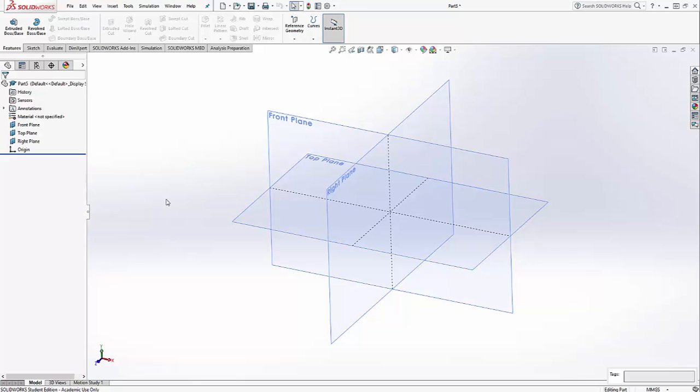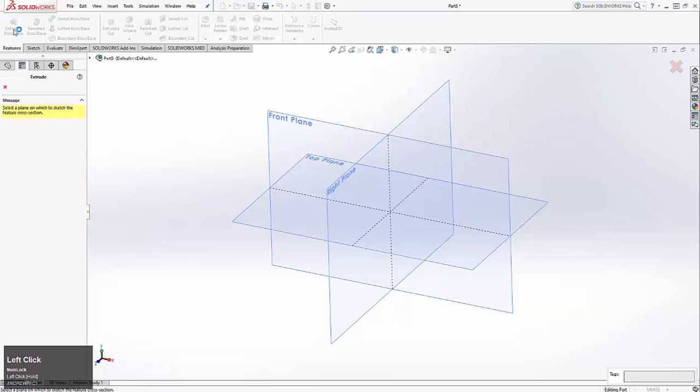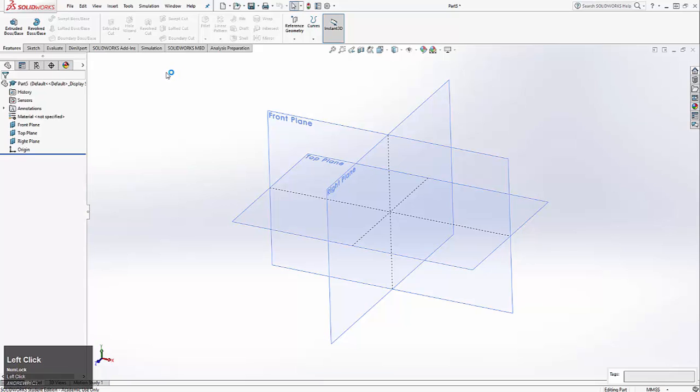So you need to make sure when you're creating a part, the first thing you need to do is actually create the base for the part. So there's 2 ways to do that in SolidWorks. You can either do an extrude or a revolve. Today we're going to be talking about extrusions. So click on Extrude Boss Base. And what that's actually going to do is it's going to sort of skip a step. And, okay, I don't want to do it this way.